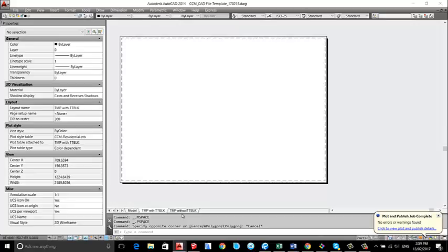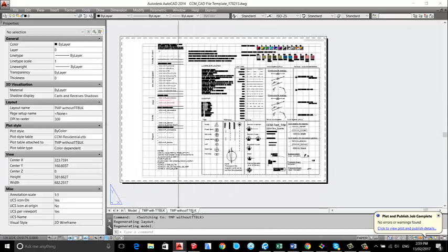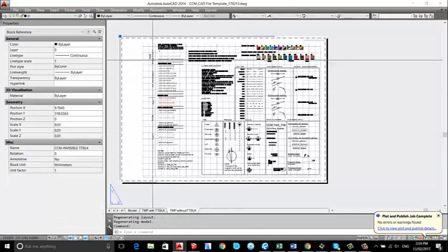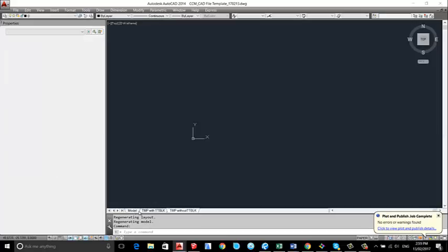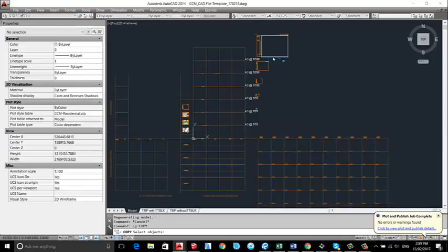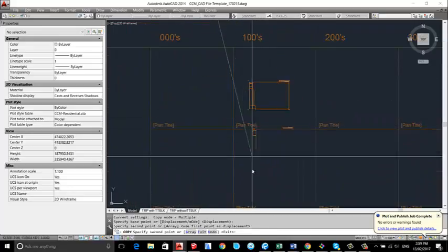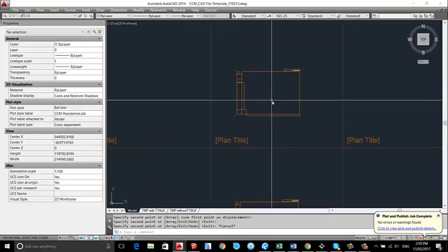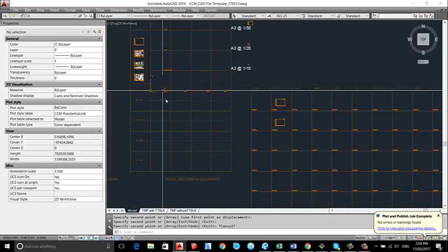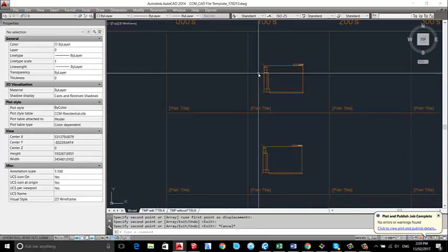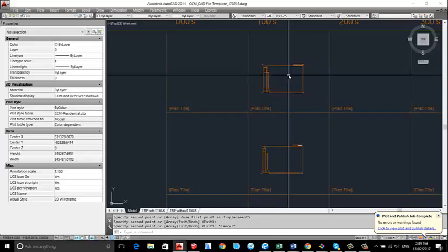But also, we have the title block that doesn't print, and we can set up different views with the graphic view. But also, as another alternative, we could populate this one, this is 1:100, and actually make the drawing in here, or reference some elevations on some plans in here with a different set of layers set up, like some layers on, some layers off, whatever.